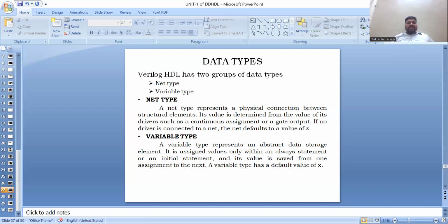Parameter port ID is 5, defined as a constant. Parameter cache line width is 256. Parameter signed [15:0] is the width, a fixed width of 16 bits, with range from 15 to 0. These are the examples of the definition of parameters.